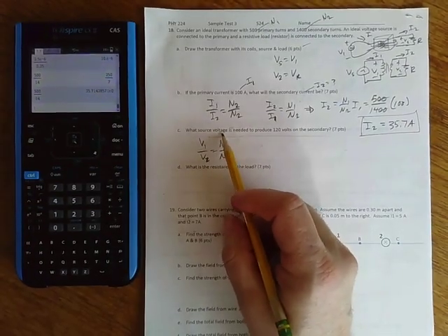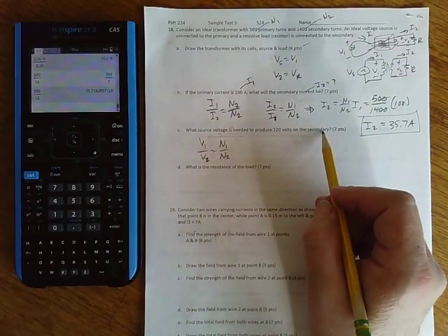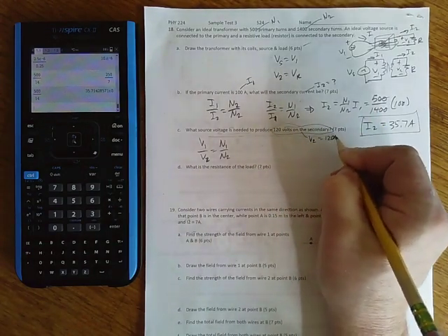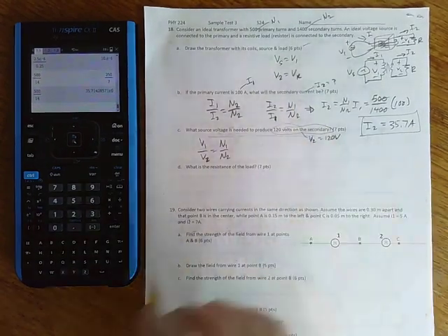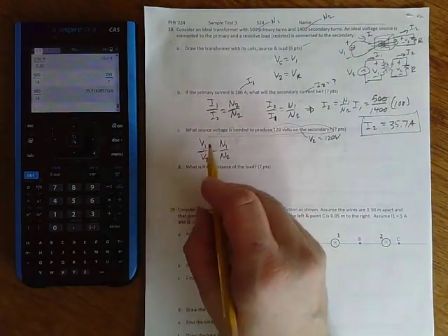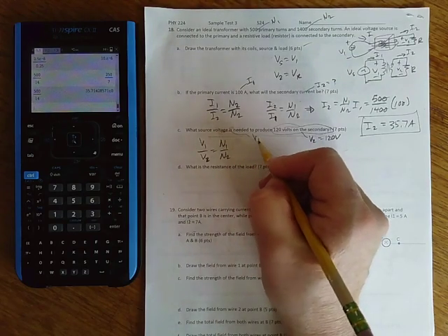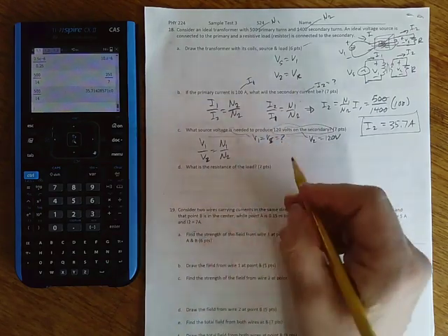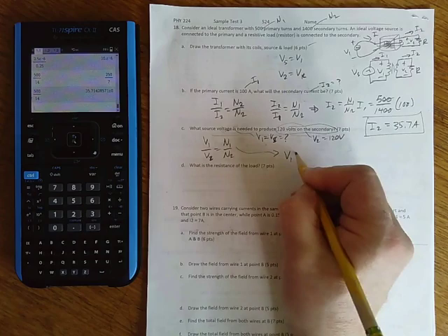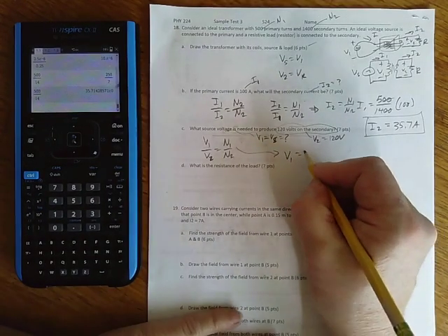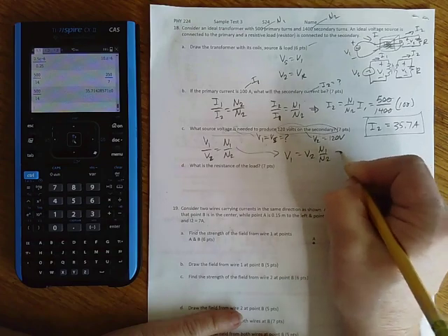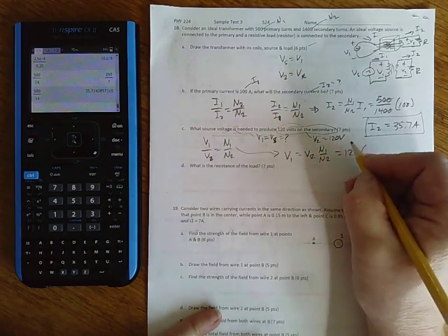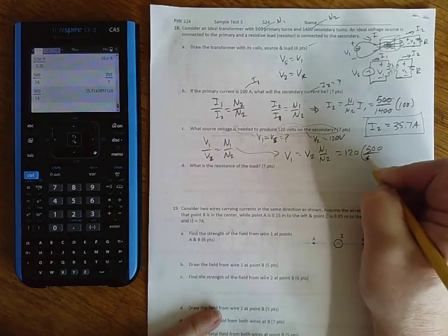Okay. What source voltage is needed to produce 120 volts on the secondary? So 120 volts on the secondary means V2 equals 120 volts. This is RMS, but we'll not worry about that right now. And so we're looking for source voltage, which means V1, which is Vs. All right, so let's solve this for V1. V1 equals V2 N1 over N2